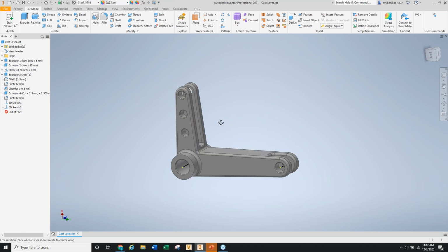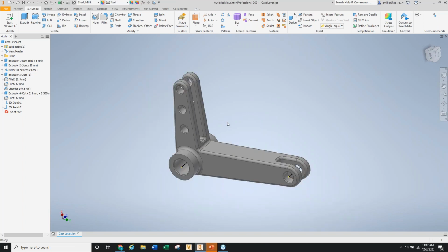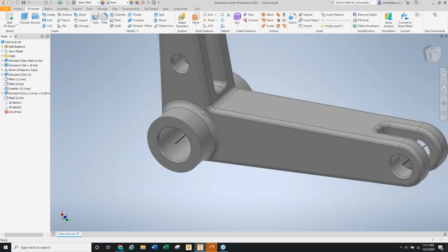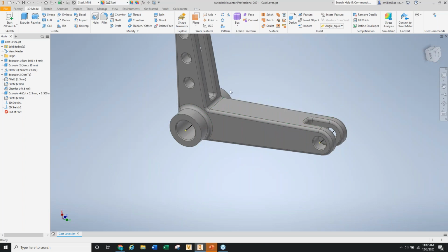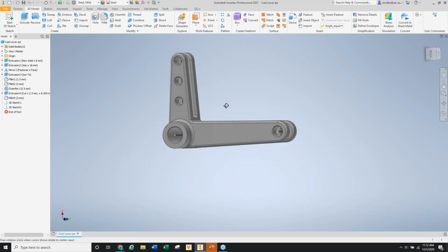A lot of times what happens is out in the field, we design this part, maybe it passed our initial test, but out in the field, it's actually failing. For instance, maybe it's cracking, maybe it's more of a fatigue situation where the initial stress of the load is fine, but over time there's enough wear and tear that we have cracks throughout. So that's a different type of analysis.